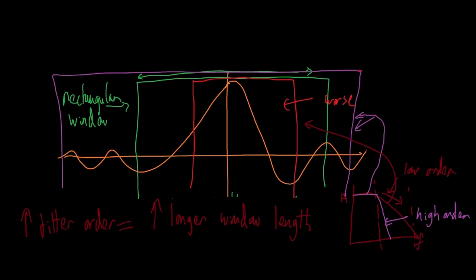Now, be wary that a higher filter order means you require more computational performance. However, it does mean a better filter performance in the end. It's important to stress that this window is always symmetric. That means it's equal on the negative side and equal on the positive side, though it may not look like it in the graph, but the window is always symmetric.